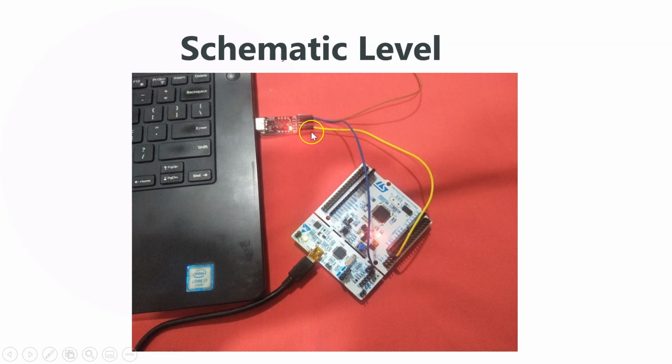So what I'm trying to do is probe the TX pin of the Nucleo board, so that we are able to read whatever data is transmitted from the Nucleo board to the computer. There are programs on the computer like PuTTY, I don't know the pronunciation or the real term. So there are some programs where we can actually specify the baud rate of transmission and observe the UART data.